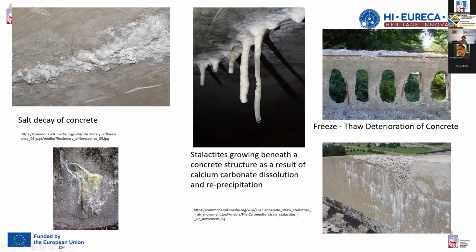almost associated with subefflorescence. This means that salts could also crystallize inside the structure of concrete. And therefore, the greater volume that is created after those salt crystallization creates some fissures and therefore deteriorates concrete a lot. Here is the case, for example.